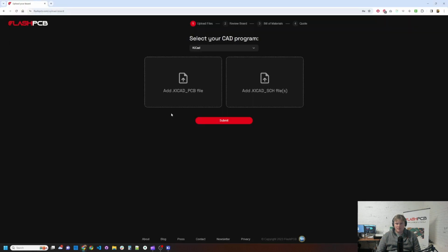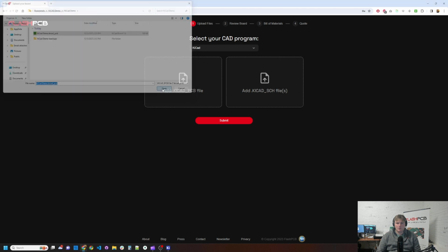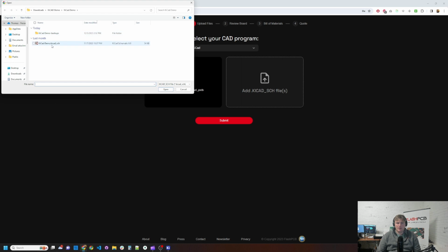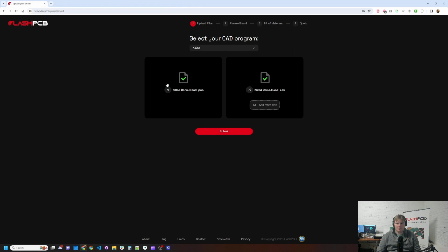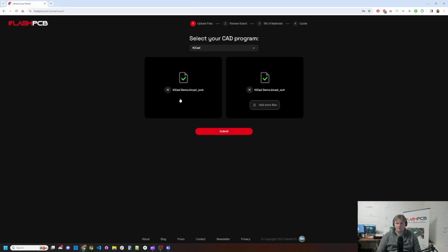So we'll go back to the website, we'll upload the board file, and we'll upload the schematic file. So we'll click Add the board file here. We'll find our demo board, we'll hit Open. And we'll do the same thing for the schematic file. So we're looking for the KiCad_SCH. Select the file. So for a simple board like this, there's only one schematic file. But if you have a hierarchical schematic, you're going to want to click Add More Files and add all of your schematic files. And then we'll hit Submit.